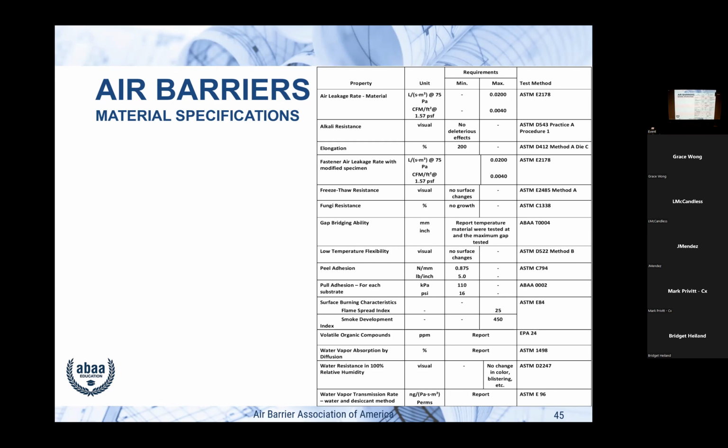Elongation is how much we can pull it apart. We have people that say, who cares? I think that's important because that gets into spraying or installing your material across a crack or a joint, and that material is going to move. So if you have a material that can't move, or it'll crack, you kind of want to know that.